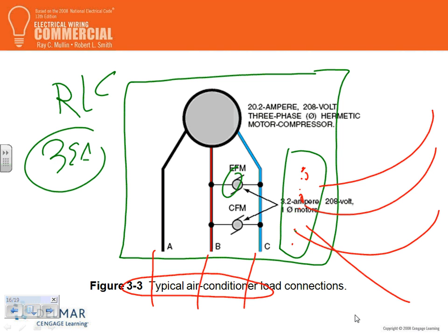That's what I'm bringing to this equipment. And I need an overcurrent protection device for this equipment. And you might have to have a disconnect right in here to disconnect it if it's not part of the equipment. Some equipment comes with a disconnect. I size my disconnect, I size my cables, my overcurrent protection device, done deal.